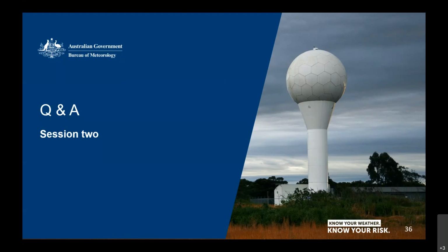That gets our signal away from the ground, so we get less clutter, so the beam doesn't hit the ground close to the radar as it's raising in elevation. That's why we like to keep it off the ground, and it also keeps the beams clear of any obstacles around the particular area. Generally speaking, most of our new towers are now going in at 22.5 metres.